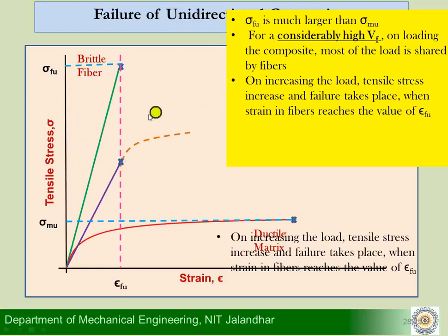So what happens on increasing the load? When you keep on increasing the load, the tensile stress increases and failure takes place. Failure of the composite takes place when the strain in the fibers reaches epsilon fu. So the failure of the fibers will take place. So the fibers will fail.